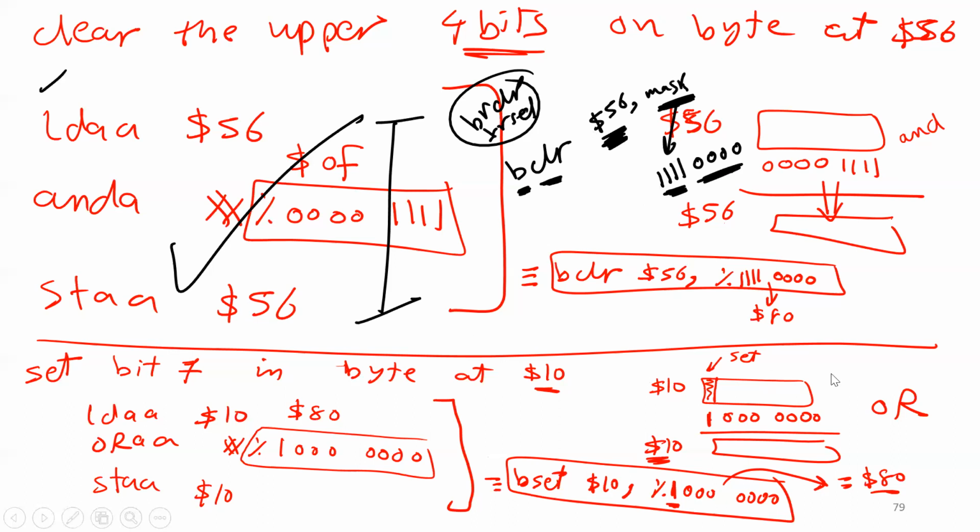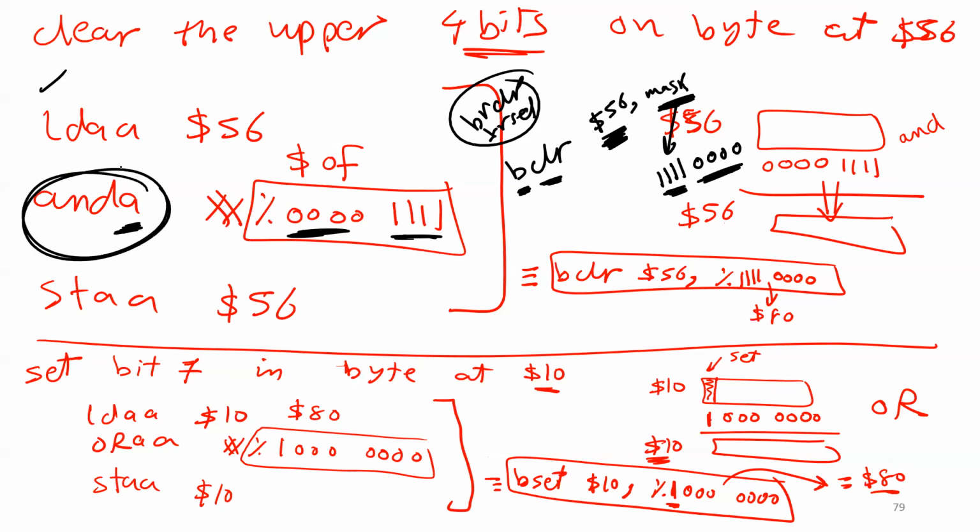I know this will confuse the student, but you need to think about it a little bit, guys. Look here. If you wanna do an AND operation, you have to put zeros here and you have to put ones here. Why? Because this is how AND works. When you put 0 here, the result is going to be 0. When you put 1, you are going to get the same bits here. This is how AND works, right? Because here you are doing an AND operation.